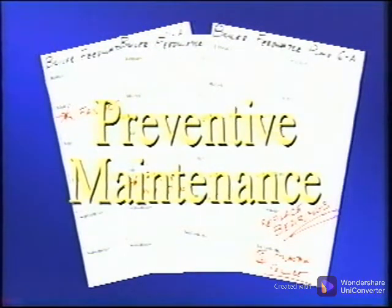Oil analysis programs in preventive maintenance plants tend to only replace the oil at calendar intervals, with the lab reports of the oil condition really having no effect on the maintenance program, and valuable information on machine condition, lube performance, and contamination is lost with each oil change.